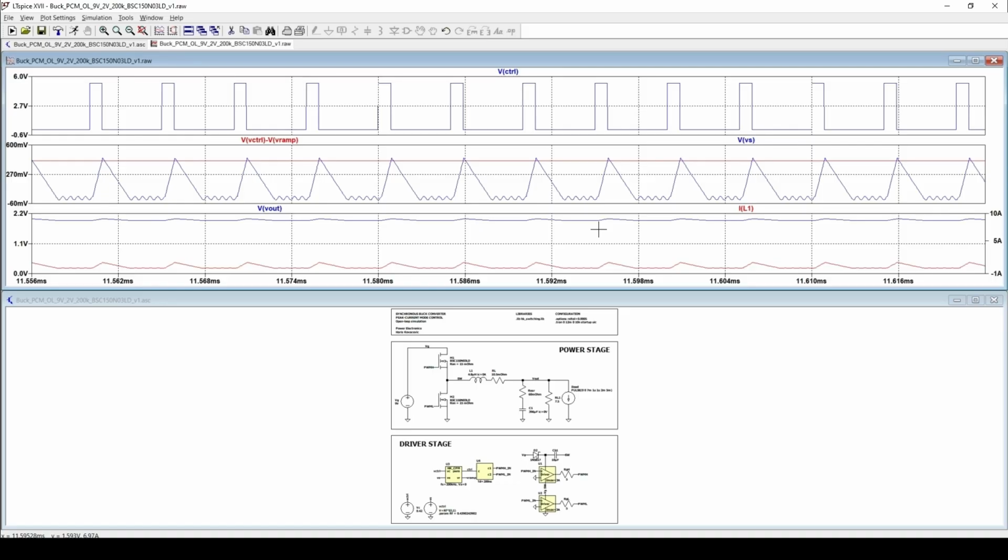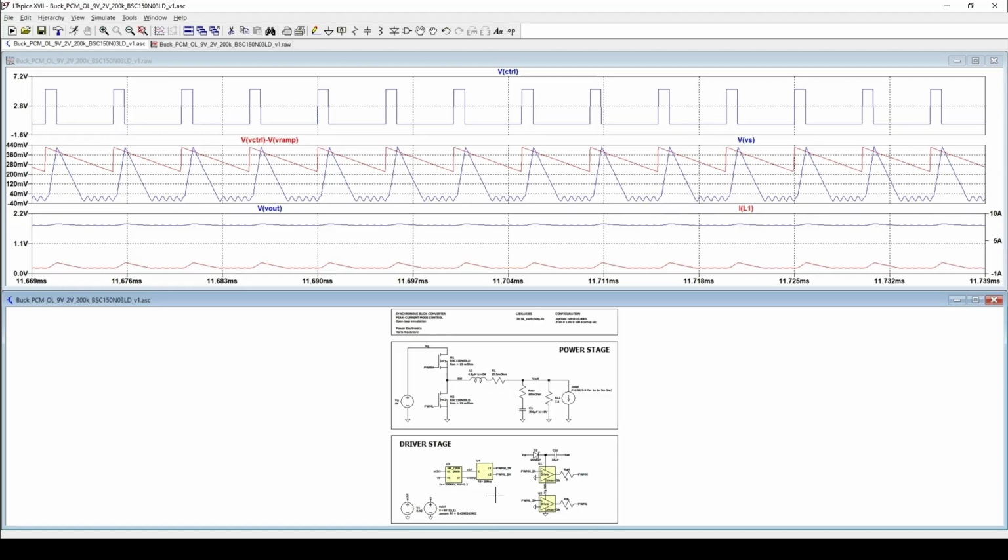What these waveforms clearly show is the essence of the peak current mode control. The duty cycle is not commanded directly. Instead, a peak current reference defines the desired inductor current level for each switching cycle. When the measured inductor current reaches the commanded peak value, the comparator trips and turns the switch off. In this way, the peak current command, not the duty command, determines the PWM pulse width on a cycle by cycle basis.